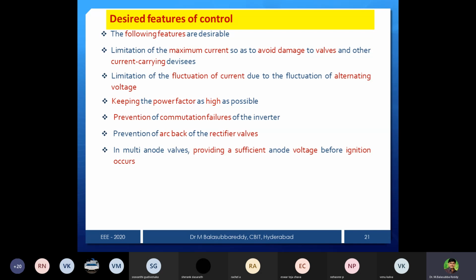Let us assume that the n minus 1 devices have a turn on time of 2 milliseconds, and the first one is 3 milliseconds, just for example. What will happen when the pulse is given to the string is that the second, third, fourth and so on valves are on. And if all the valves are in parallel, and the other valves are conducting, then automatically the voltage across that will be very minimum. It is only 1 to 2 volts.